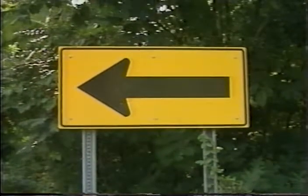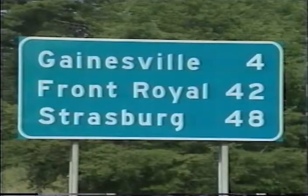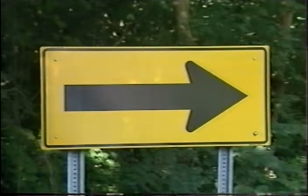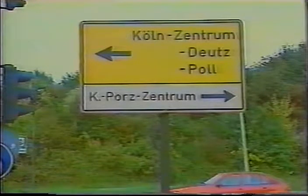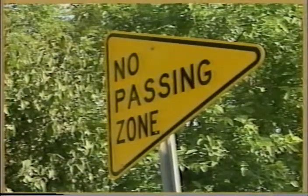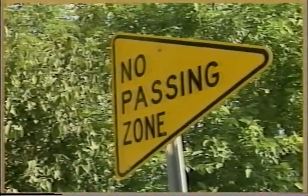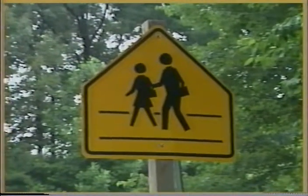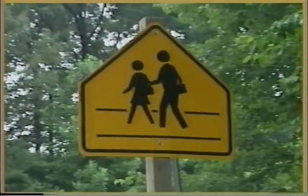With the longer dimension horizontal, the U.S. and Latin American systems use the rectangle for a majority of guide signs and some warning signs. However, the European system uses this shape for informative signs. A pennant shape with the longer part horizontal is used only in the U.S. for no passing zone warning signs. A pentagon with a point up is also used only in the U.S. for school and school crossing signs.